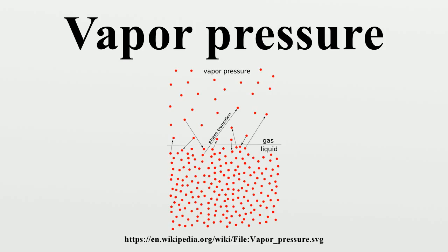Relation to boiling point of liquids. As a general trend, vapor pressures of liquids at ambient temperatures increase with decreasing boiling points. This is illustrated in the vapor pressure chart that shows graphs of the vapor pressures versus temperatures for a variety of liquids. For example, at any given temperature, methyl chloride has the highest vapor pressure of any of the liquids in the chart. It also has the lowest normal boiling point, which is where the vapor pressure curve of methyl chloride intersects the horizontal pressure line of 1 atmosphere of absolute vapor pressure.